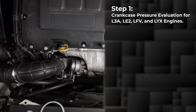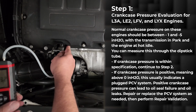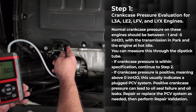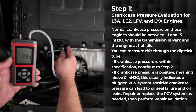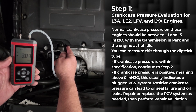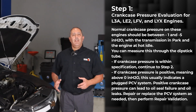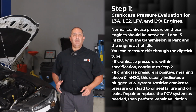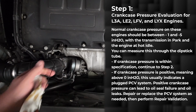Step 1, check crankcase pressure evaluation for L3A, LE2, LFV, and LYX engines. Evaluate the crankcase pressure on the engine. With the engine at normal operating temperature, the transmission in park, and the engine idling, crankcase pressure should typically measure between -1 and -5 inches of water. This measurement can be taken through the dipstick tube using a manometer. In this case, the crankcase pressure reading falls within specification, indicating that the positive crankcase ventilation, PCV, system is operating as intended. Continue to the next diagnostic step.